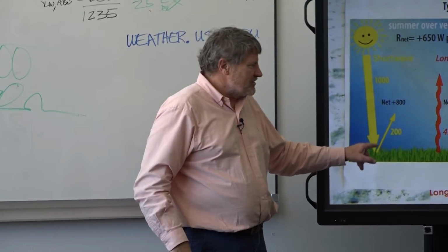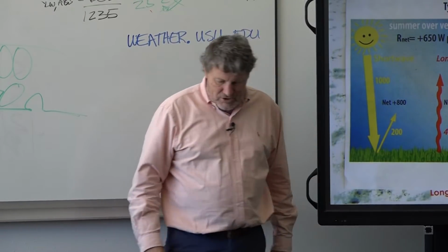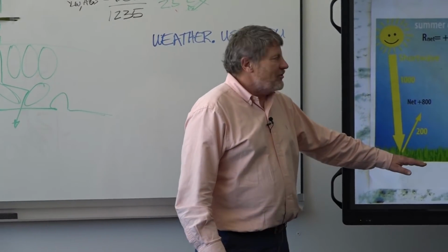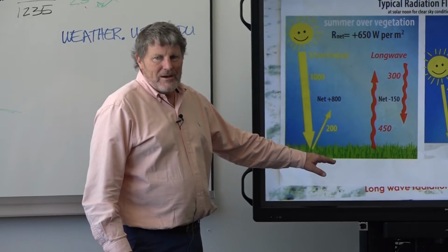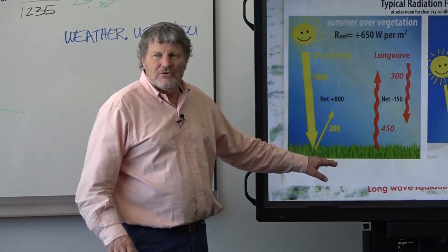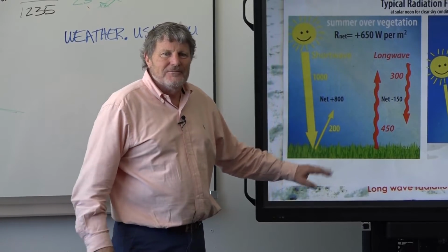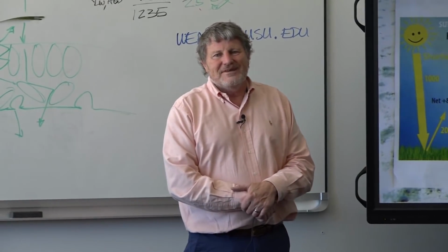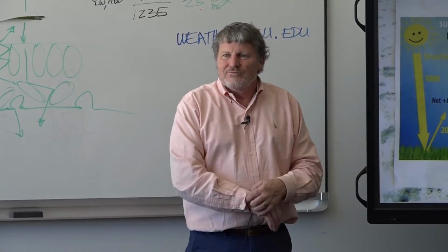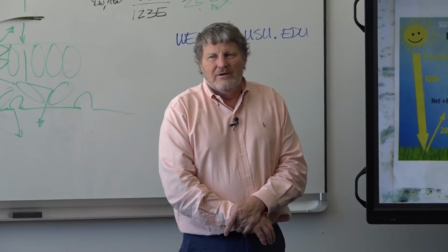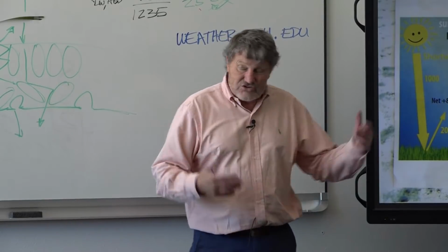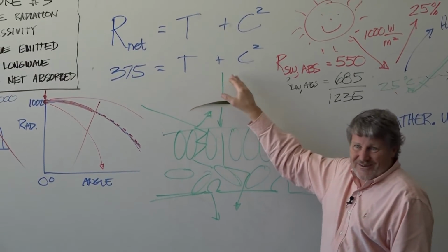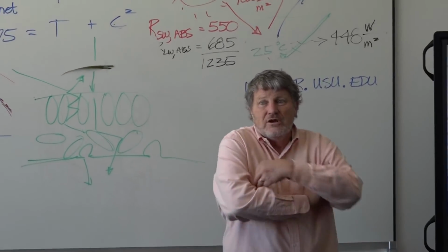It's FAO 56. Since then, Blomqvist et al. did a big study with a bunch of net radiometers, and as I recall, nearly all of the net radiometers were more accurate than the models. The only ones that weren't were the very cheapest models. It was all, actually. All, even the cheapest net radiometers. So that's the evolution of instruments. They're better and cheaper. And man, you can see, if you can get this number right with an instrument, wow, you're getting there, because now you just got a couple other components.